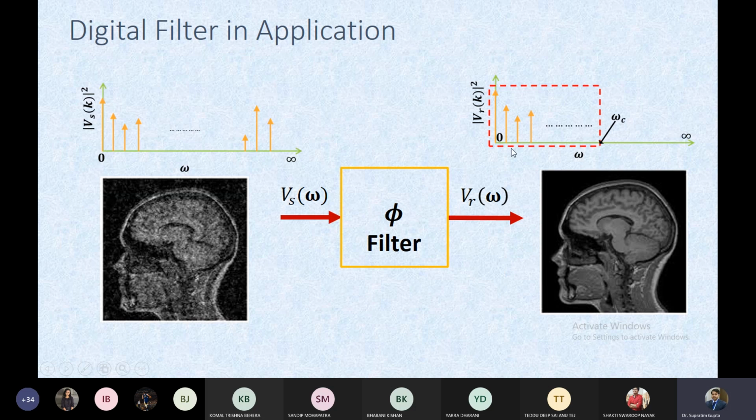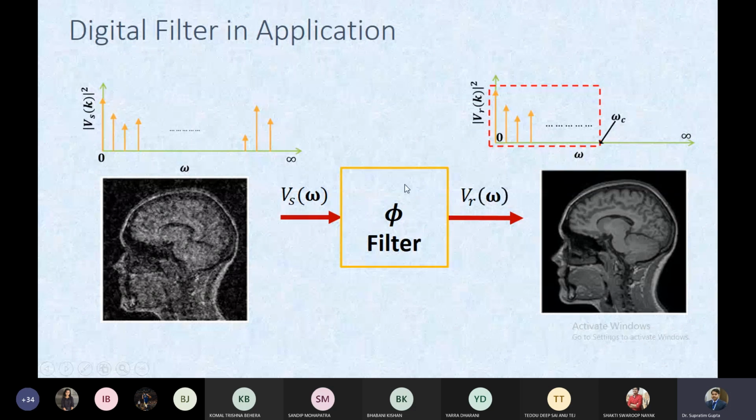So that means, for example, we have 50 hertz, then 100 hertz, then 200 hertz, like that, all these frequencies. Okay. So my point here is that whenever we test the filter's frequency response, we need to pass a signal of a particular frequency, say 50 hertz, and check the output at the end of the filter, whether it is 50 hertz or not, if it is within omega c. So if 50 hertz is within omega c, then the signal should be as it is at the output of the filter.